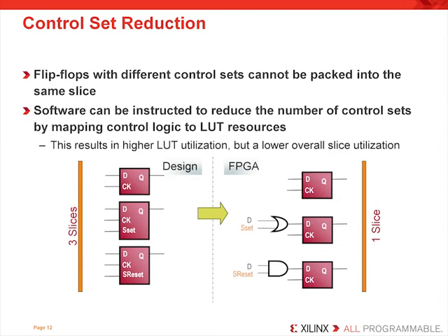But since the lower flip-flops require a synchronous set and a synchronous reset respectively, the designer's synthesis tool or the Xilinx implementation tools can remap the logic to a LUT input rather than a flip-flop control port. This will allow the implementation tools to group the flip-flops into the same slice. Now, by the way, the reduce control sets property for XST synthesis controls this result, but if you don't design with a synchronous set or reset, it won't be used.